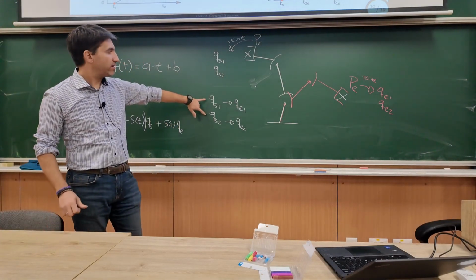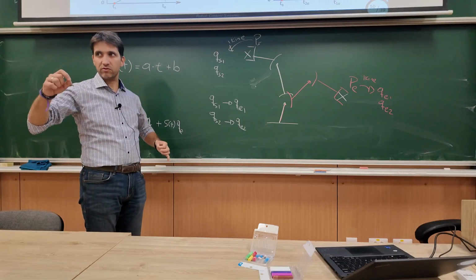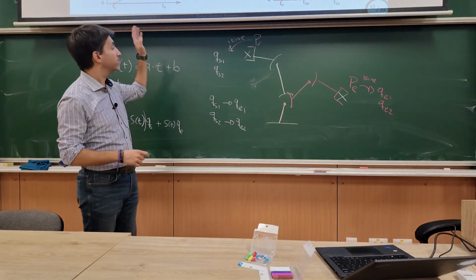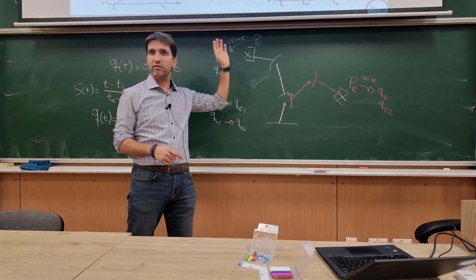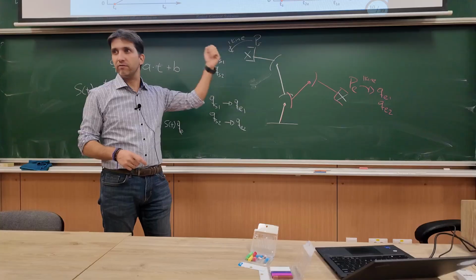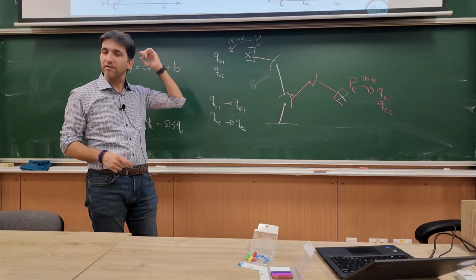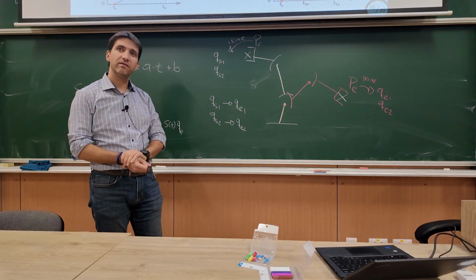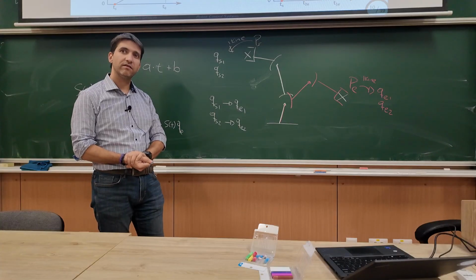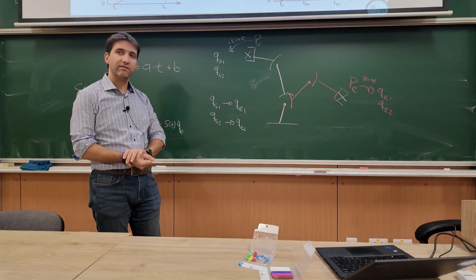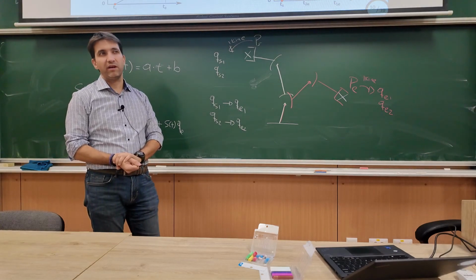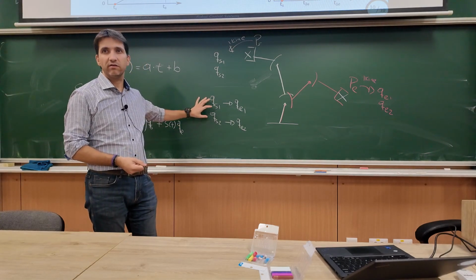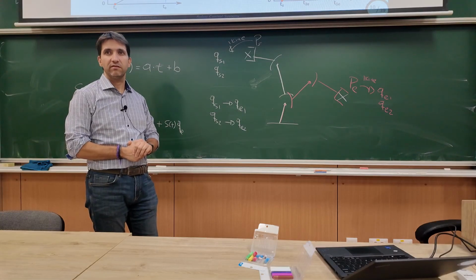If I move at the joint level linearly, so I move the joints following a line, right? Do I expect the same behavior for the end effector? If yes, why? If not, why? Because only the variation of the joint angles is linear. Alright, and the pose of the end effector, what relationship does it have with the joint coordinates?